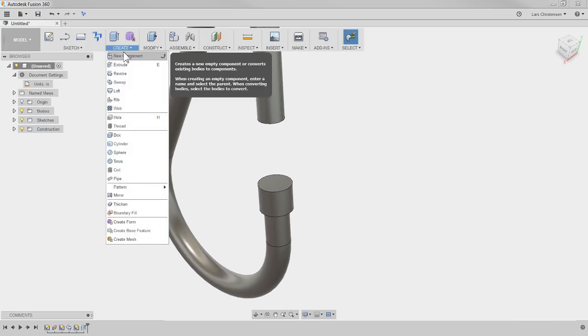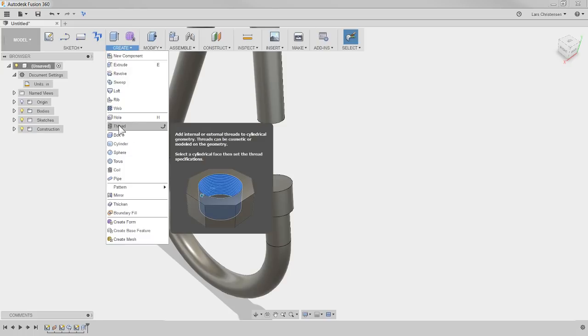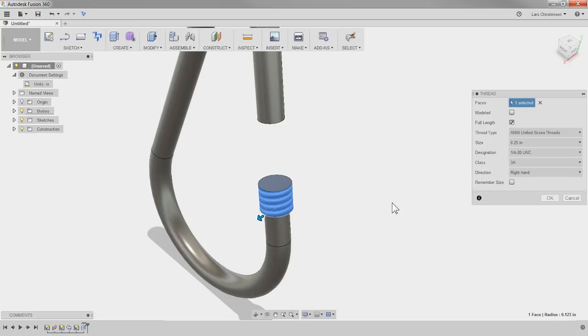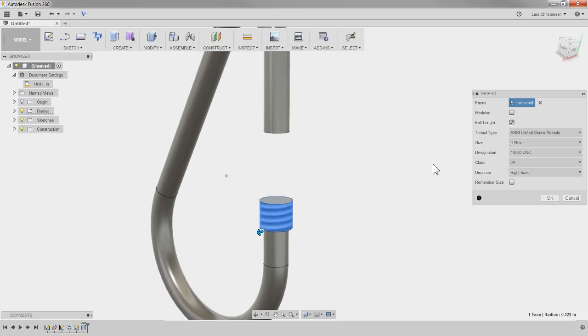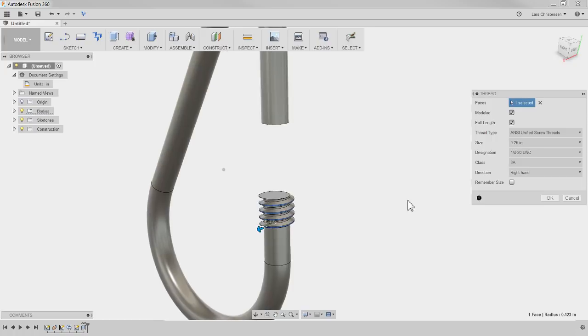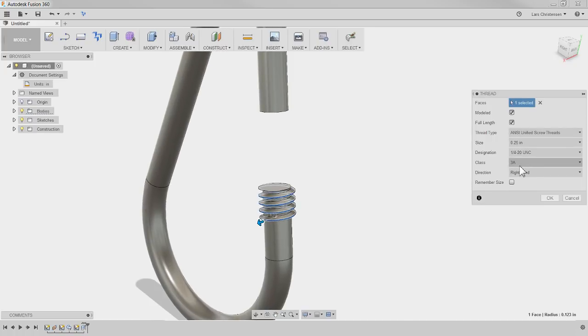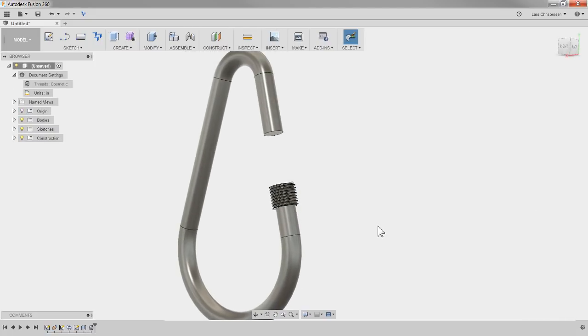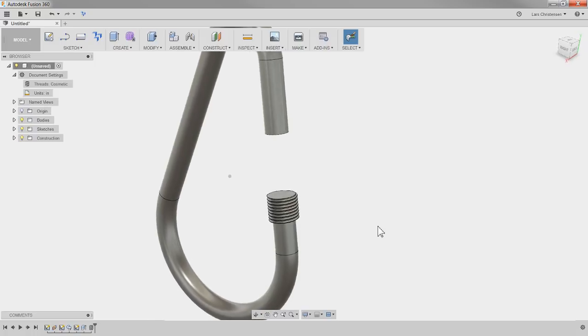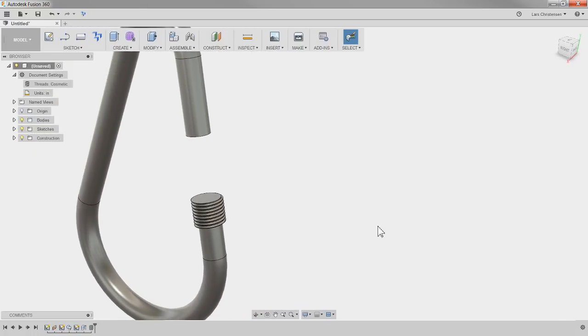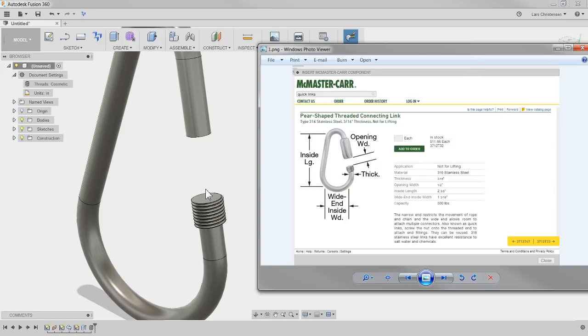And then we could go in here and create the thread by clicking the thread command here, and select that face. By default, it's going to be the bitmap. We talked about that in the live stream before. But of course, you can go in and select modeled, and then you get out of the Machinist Handbook all these different ones. Now, these are normally very fine threads on this type. So maybe select a finer thread. So then we get this component here. Now, I wanted to get to this point on purpose because now you suddenly realize that, well, no, you don't.